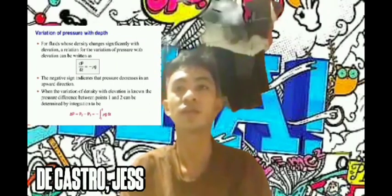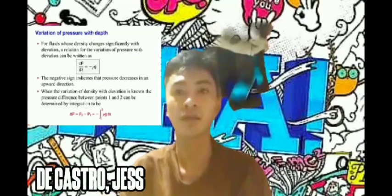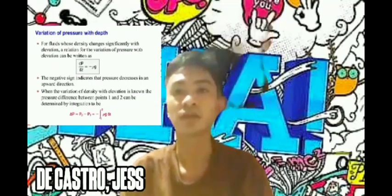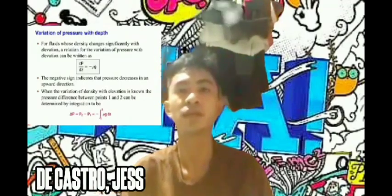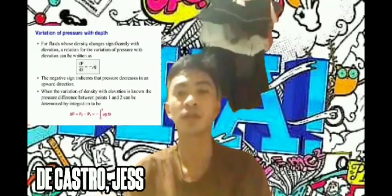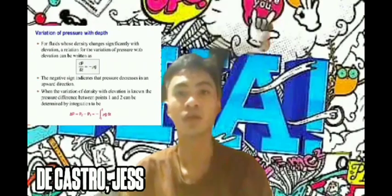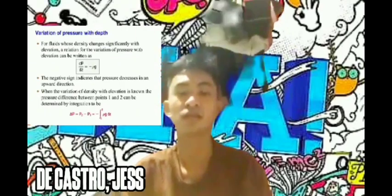For fluids whose density changes significantly with elevation, a relation for the variation of pressure with elevation can be written as dP/dz equals minus rho g. The negative sign indicates that pressure decreases in an upward direction. When the variation of density with elevation is known, the pressure difference between points 1 and 2 can be determined by integration to be delta P equals P2 minus P1 equals negative integral from 1 to 2 of rho g dz.